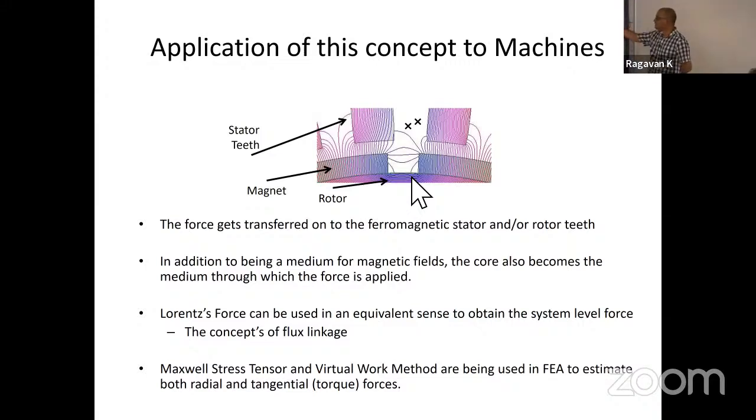Like if you have this core, you will have an average flux density, say 0.8 in an NdFeB SPM machine or IPM. Whereas if you go into that slotless machine, you'll have 0.2 or 0.3, right? So it's like even a magnet suspended in the air has magnetic field. So you're using a field strength that's similar to that to run the motor. So there is a field. It's not that in a slotless case, there is no field. Did I answer your question?